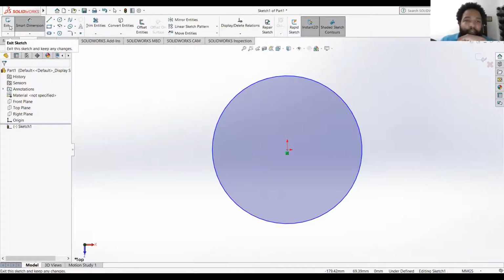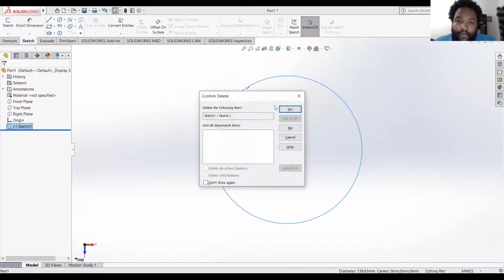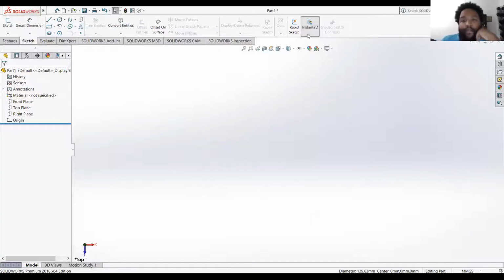But one thing I did miss, which, let me erase this. This model is going to be in inches. So we're going to have to go down here. I have my settings set to millimeters, grams, and seconds. But since we're going to be using inches, we're going to have to switch to the American units, which are inches, pounds, and seconds for anything.